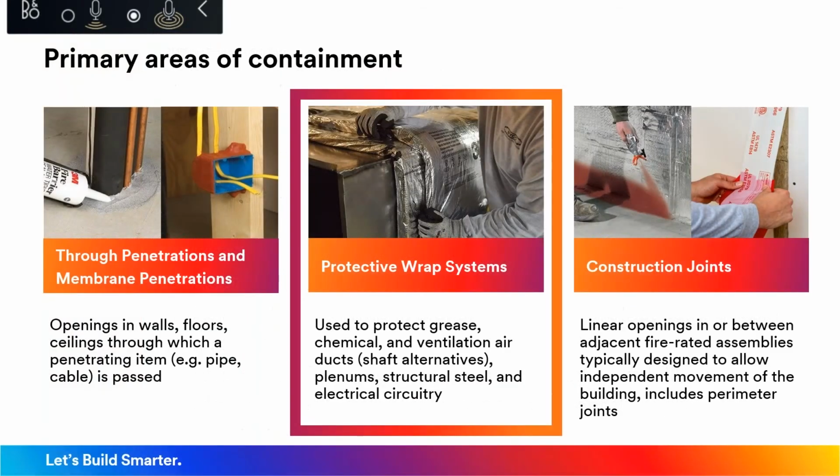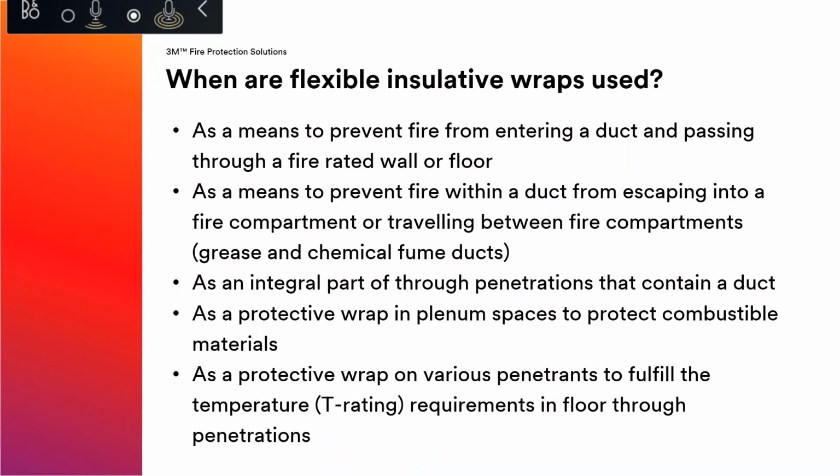So, flexible wraps. So when are flexible wraps used? Typically in our industry here, from an insulation supplier's perspective, especially these flexible insulative wraps and mats are used as shaft alternatives. They're used to maintain a fire within a duct or keep it from entering a duct.